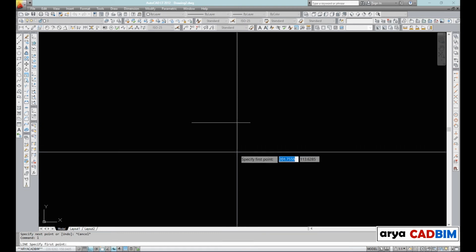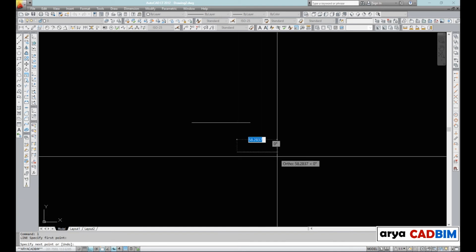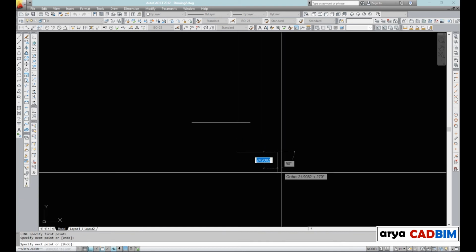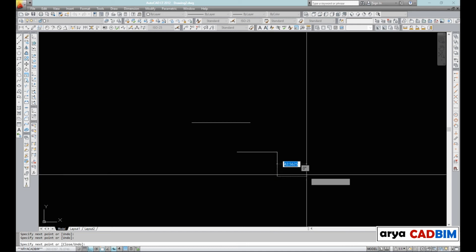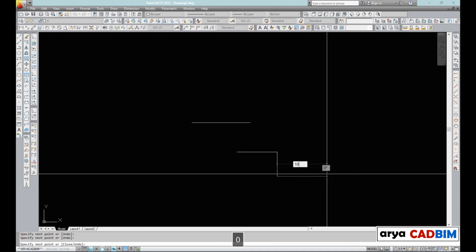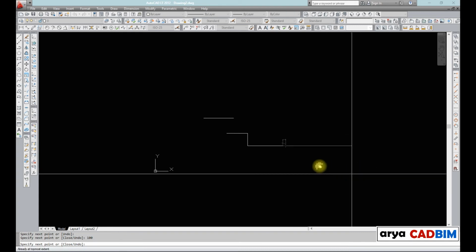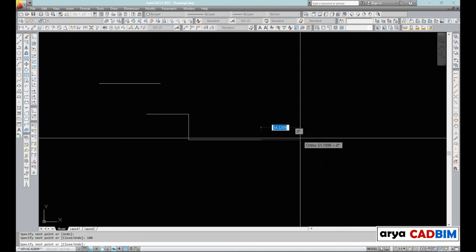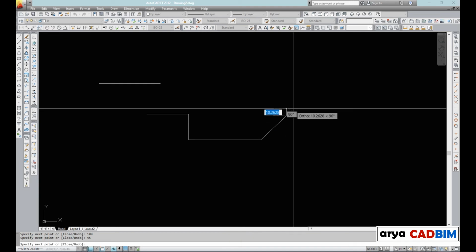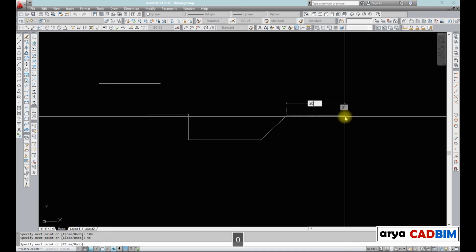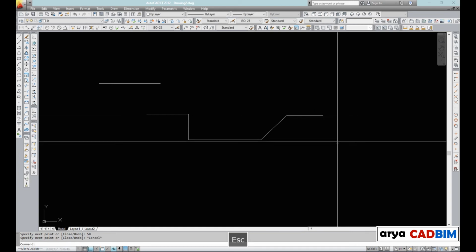When dynamic input is on, tooltips display information near the cursor that is dynamically updated as the cursor moves. When a command is active, the tooltips provide a place for user entry. After you type a value in an input field and press Tab, the field then displays a lock icon, and the cursor is constrained by the value that you entered. You can then enter a value for the second input field. Alternately, if you type a value and press enter, the second input field is ignored, and the value is interpreted as direct distance entry.